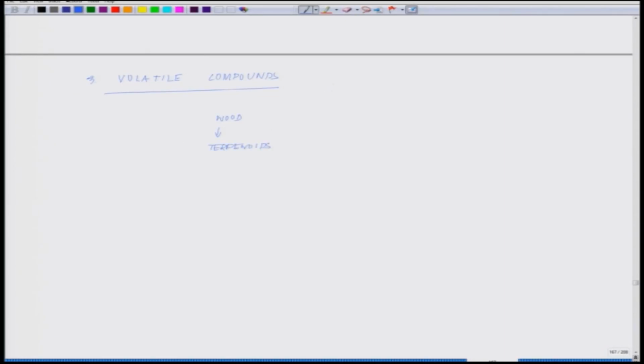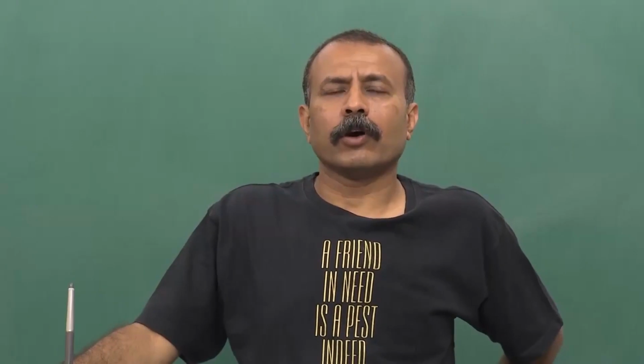What is very important is that if the feedstock has a lot of volatile material, then the gasifier you choose for your industrial work should be able to destroy the tars, which are basically the product of all the terpenoids, and should be able to destroy the heavy hydrocarbons, because these are a source of different kinds of volatile material, and most of these volatile materials are not very healthy for humans to be exposed to.